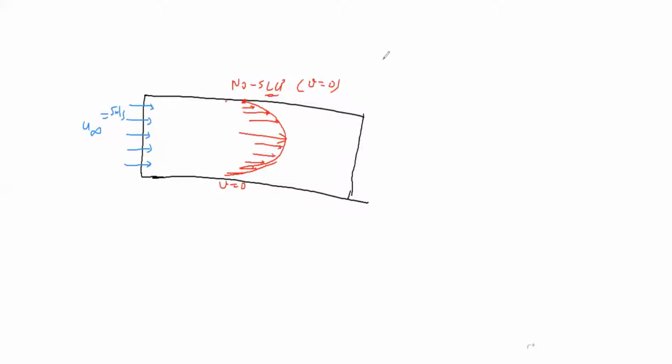The thing you were talking about, the shear stress, is a different thing. Here what we are interested in is dou u by dou y. Let's say this is your y and this is your x. We are not interested in du by dx, which is very small, but dou u by dou y. At the center there is no resistance, but as we move towards the wall, the first layer is resisted by the wall of the duct, and the next layer will resist, but this effect reduces, and at the center there will be maximum velocity, which is u infinity.